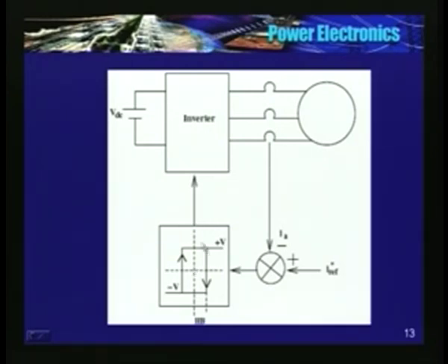By the way, this hysteresis band is nothing but a Schmitt trigger. Okay. So this is a subtractor, op amp circuitry again. This is another Schmitt trigger. I have shown you here only for one phase, and I showed you there are 3 current sensors to measure the instantaneous current that is flowing into the machine. Remember, it is the instantaneous current that is flowing into the machine that is controlled.